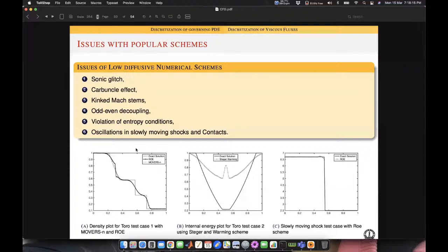Because of this approximation, you have non-smoothness, you have unphysical shocks. You don't predict the values. Say, in the first figure you have an expansion shock. That is unphysical. For a regular perfect gas equation, that is unphysical in nature. So you don't want that in your numerical simulation. If you get something like that, it is not a valid solution.